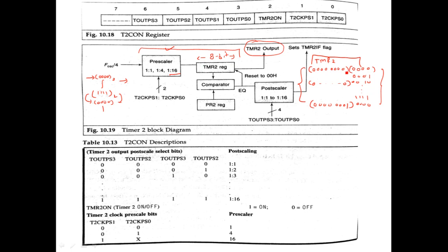8 bits in the TMR2 register, along with 2 least significant bits which are taken from the prescaler. Out of 4 prescaler bits, 2 bits will be taken here. So now you understand that here also you have a 10-bit count. In this progression, you can forget about the last 2 significant bits and focus on these 10 bits, and the way in which these are changing, those 10 bits will be compared by the comparator in the PWM module with the 10 bits in the CCPR1L register.